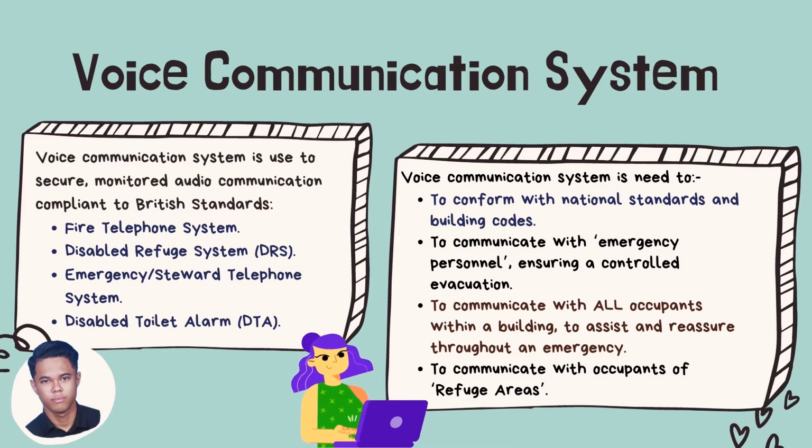Okay, in this topic, I will explain about voice communication system. Voice communication system is used to secure monitored audio communication compliant to British standards, which are the fire telephone system, disabled refuge system (DRS), emergency steward telephone system, and lastly, disabled toilet alarm (DTA).